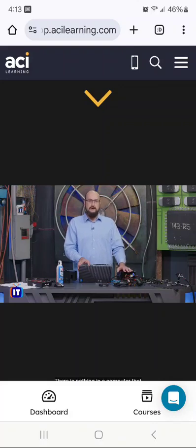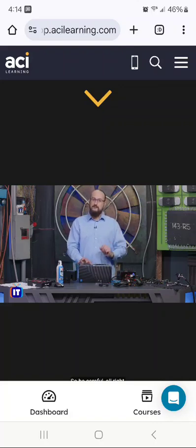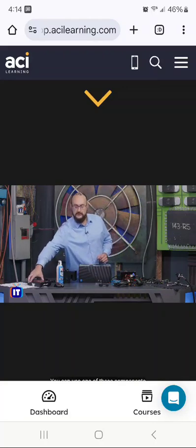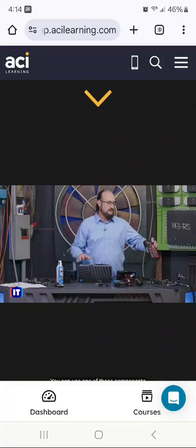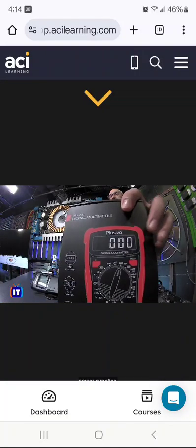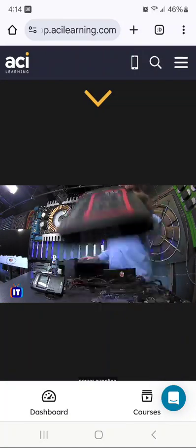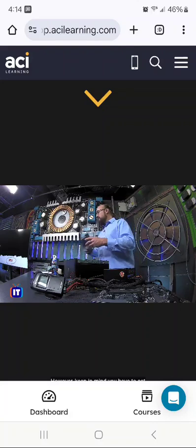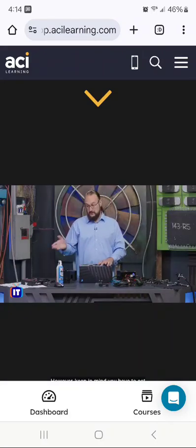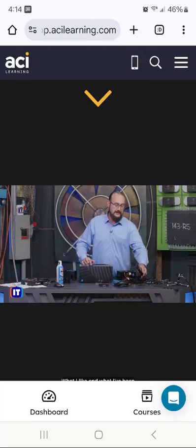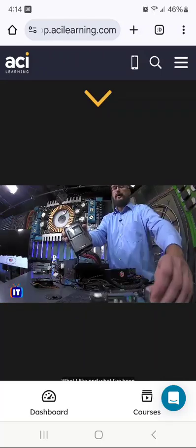There is nothing in a computer that is more valuable than you are. So be careful, all right? There are things that you can do. You can potentially use one of these components if you need to test power supplies. This is a multimeter. However, keep in mind you have to set it to the appropriate voltages, or you could fry the multimeter too. What I like and what I've been using here is this component here.